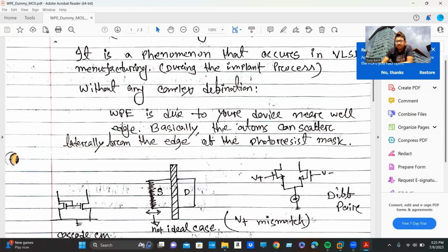For digital circuitry, where basically the voltage is shifting from one level to another level, VGS matching, VDS matching, and threshold voltage matching are not as important as in analog circuitry, because analog circuitry may be easily affected by temperature, noise, supply voltage mismatch, threshold voltage mismatch, any kind of mismatch.